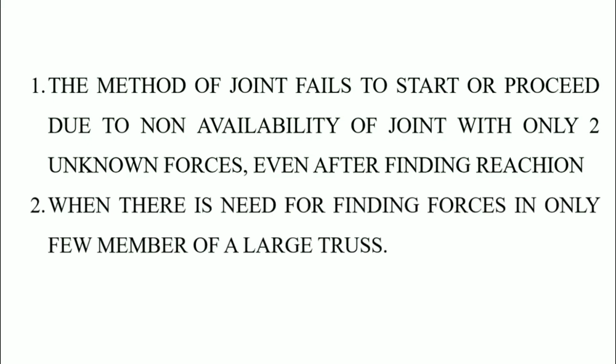The second case is when there is need for finding force in only few members of a large truss. Suppose we got a large truss, we have to find only few forces. Just we go to the method of section than method of joints because method of joints is so complicated and it is a time-consuming process. Now we are going to discuss about how can we find out the member force using the method of section, or steps to find out the force in member using method of section.